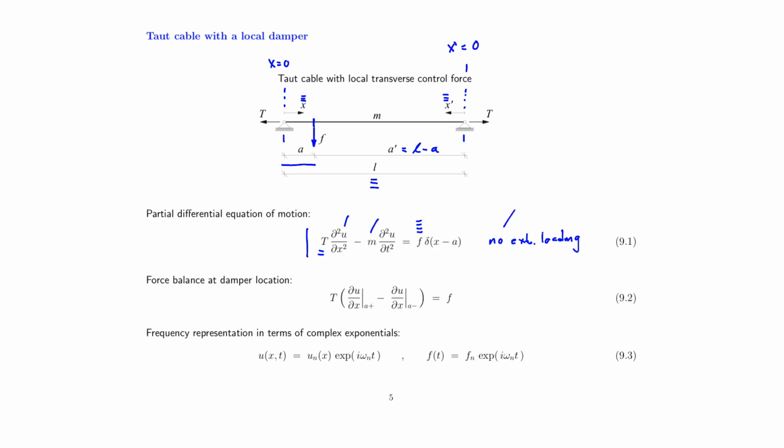So we are actually doing a so-called free vibration analysis, like we did for the cables in lecture number 5, and that means we are looking for an omega n, and in particular also a vibration shape. Today we will not use capital X. Instead we will use u n as a function of x. These two are comparable if you want to compare this lecture with that of lecture number 5.